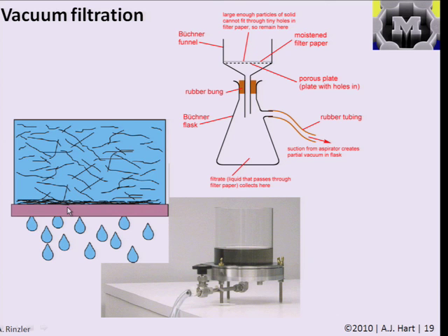And then after this, you could take this membrane out and you might be able to transfer the film to another substrate, and in often cases these processes use thin polymer membranes that can be dissolved in solvents. So in fact you could dissolve that polymer membrane away and have a freestanding film that you could then pick up and put on a substrate, or just print onto a substrate and then peel the polymer or dissolve it